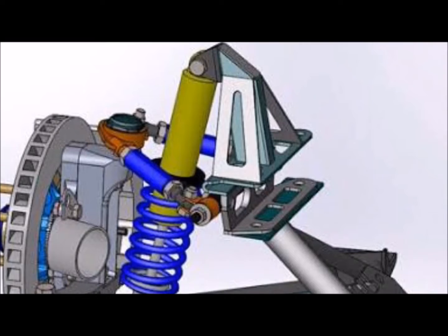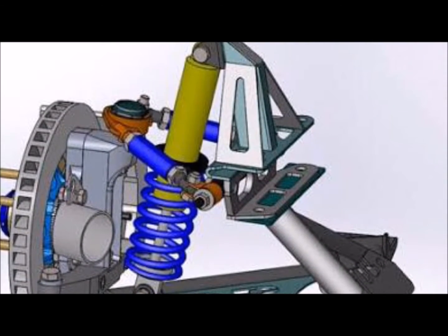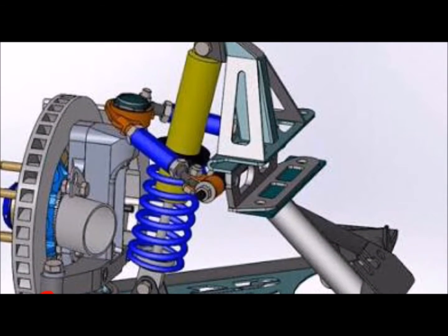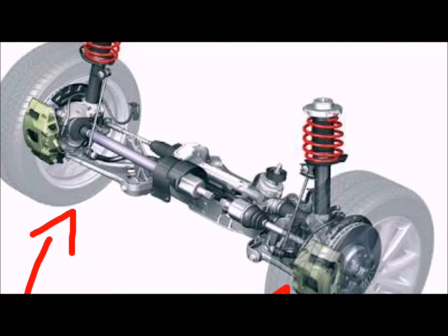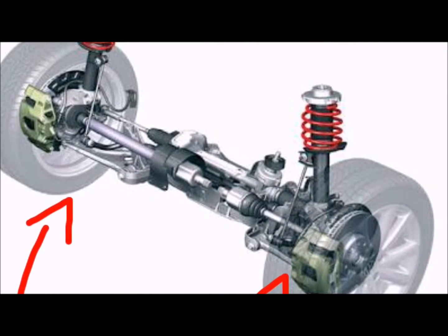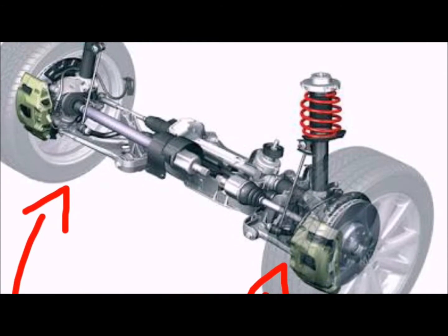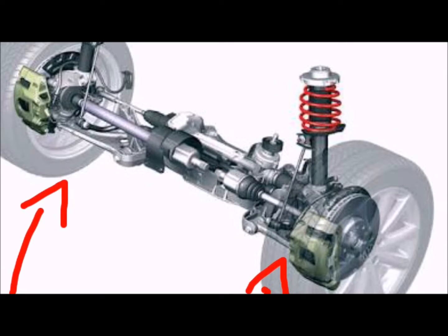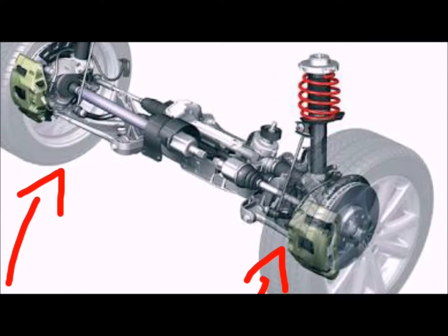In the SLA suspension, when the force is applied, the whole suspension is going to move vertically. This displacement is known as ride rate. As you can see, it can be upwards or downwards. Now we have a McPherson suspension. As in the SLA suspension, when the force is applied, the red arrows, the system will have a vertical displacement, and this is the ride rate. The displacement depends on the force, so if the force is bigger, the displacement is going to increase.